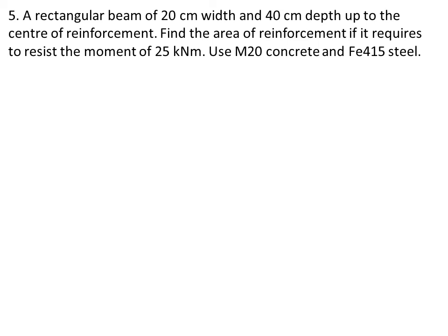Okay, this is the fifth question. A rectangular beam of 20 centimeter width. Sometimes it can be given in centimeters as well as meters. Since we are using millimeters throughout, while drawing we can convert it to mm, that is 200 mm, and 40 centimeter depth up to the center of reinforcement. That means it's the depth up to the bar, that is the effective depth.